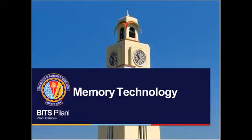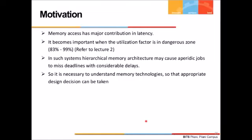So we talked briefly about processor technology. Let us go to the next important part of hardware of a real-time system, that is memory. You definitely will know that memory accesses have the major contribution in latency. Basically, if you want to make a system faster, then look at the memory accesses rather than looking at how fast the processor can perform. Of course, you have to look at how fast the processor can perform, but having a very fast processor and very slow memory access will not improve your system, rather it will be limited by the memory access.